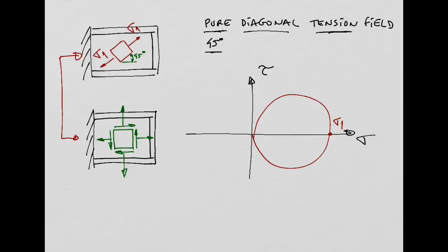Now, this angle here, 45 degrees, is the angle that we need to use for our stress transformation. In the Mohr circle, we always use 2 times this angle, right? So look at this. This is the center of my Mohr circle. If I have 45 degrees there, in the Mohr circle I need to have 90 degrees. So this point here, this angle is 90 degrees, right? Yeah?